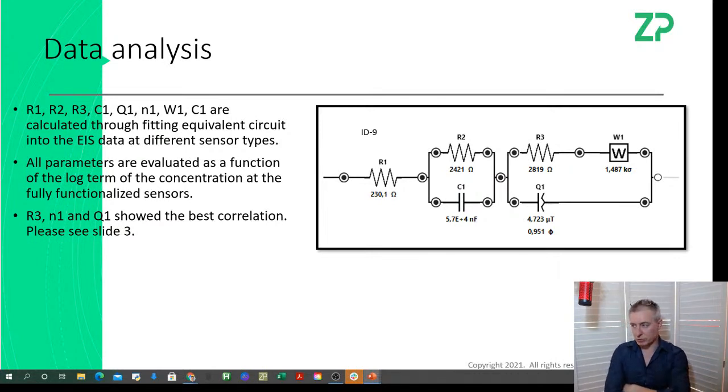You just try them both and see which one works. So cyclic voltammetry for immunosensors, I don't think works particularly well. We have had good success with square wave voltammetry and differential pulse voltammetry. I think Hasim, who's online today, has got quite a lot of experience with differential pulse voltammetry. But the technique that actually works the best, in my opinion now, for immunosensing work, is unfortunately impedance spectroscopy. Now, I think that the guys that asked the question don't have a board that could do EIS, but unfortunately, EIS is the best technique.